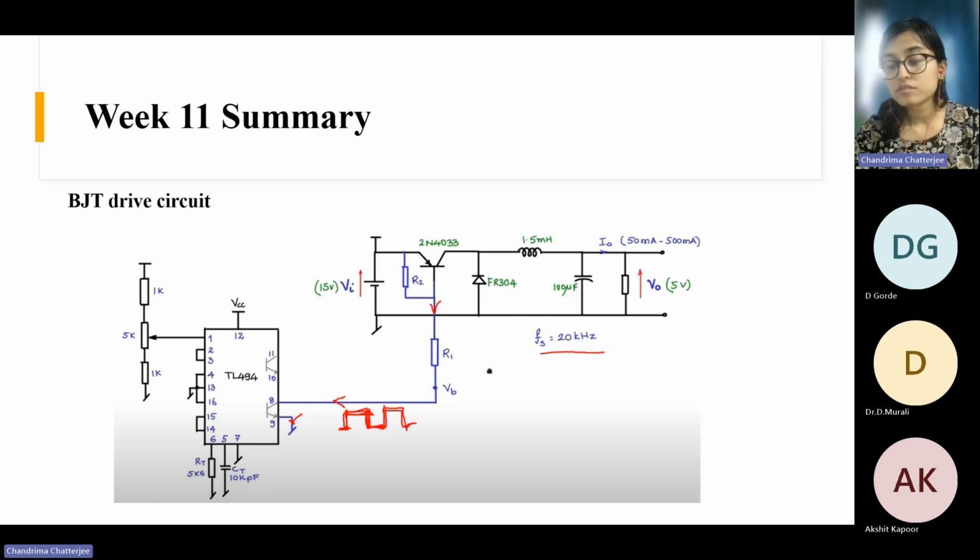You have to design the RT and CT values so that you can dictate your on time and off time. Maybe they are called precision components because their values have to be very precise so that you can control the transitions. I am not sure exactly why they are called that. I will have to check, and if I find the answer, I will tell you.